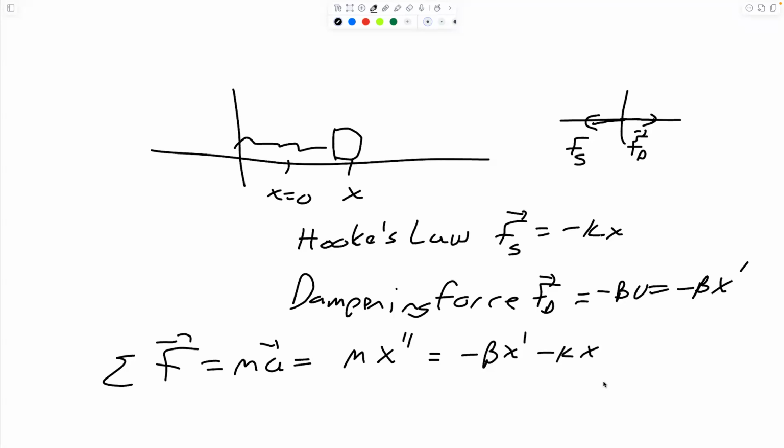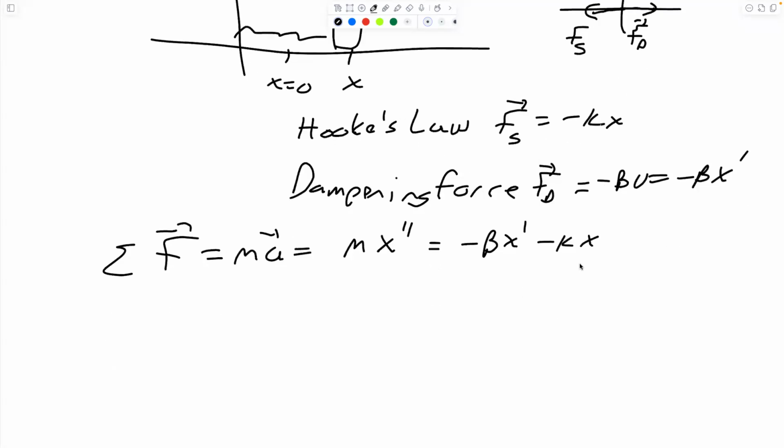Literally everything here I go through in that lecture video, and I go through all the basic cases when we have overdamped, underdamped, and critically damped. So we don't need to re-walk through all that. You may mention here, recall that the professor went through all this before. You're just refreshing people's memories. We put this in standard form, mx double prime plus beta x prime plus kx equals 0.